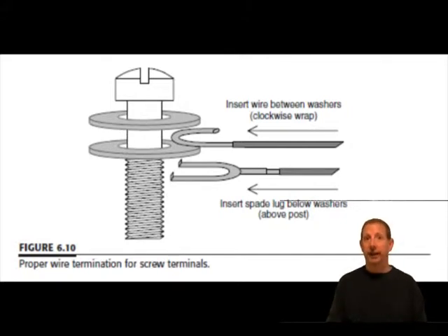It is also a good idea for LAN circuits to try to maintain as much of the pair twist as possible up to the point of termination. Now, some authorities recommend trying to limit the untwist of Cat 3 cable to no more than 1.5 to 2 inches.